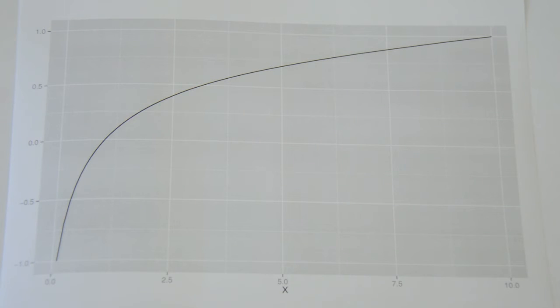So why are we interested in sampling in the logarithmic domain in the first place? Let's say you're building an instrument to measure signal power, like the spectrum analyzer. If you want to measure weak signals and changes in that weak signal, your instrument is going to be pretty sensitive to these changes. But this also means that if you apply a strong signal, you're probably going to overload your instrument because it was designed to handle weak signals and changes in weak signals. So it wasn't designed to handle strong signals.